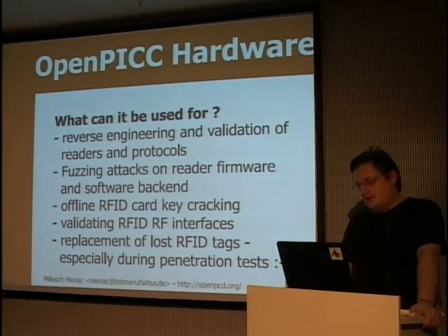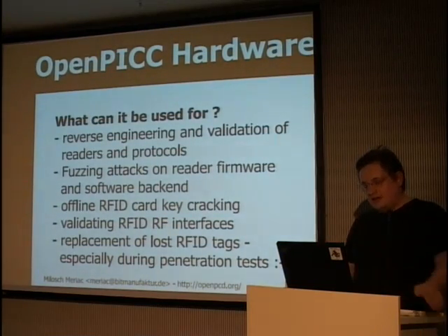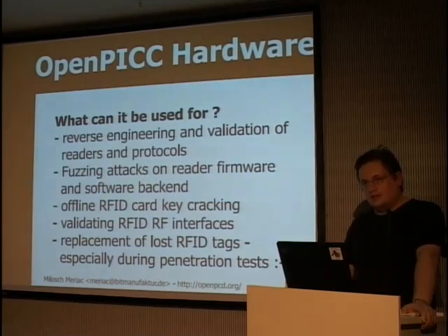One main use case is also fuzzing attacks. Because we are in full control of even the lowest layers of the protocol, we can introduce all kinds of violations. So you can watch me automatically violate different areas and look at how the readers react to it, if it breaks, if it stops.